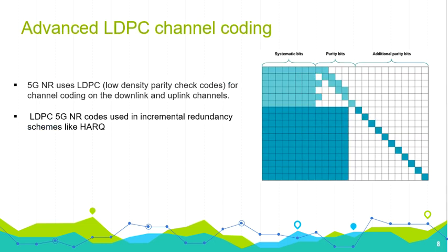There is an advanced low density parity check code for the new radio 5G. I remember doing a project on a telecommunication subsystem, designing the IQ modulator. When I implemented the model of transmitter and receiver, with modulation and demodulation, I saw a lot of bit error rate on the receiver side. But when I implemented it with the help of LDPC coding, I saw the bit error was reduced very much. So I can imagine this technique is also very helpful to reduce errors in communication.